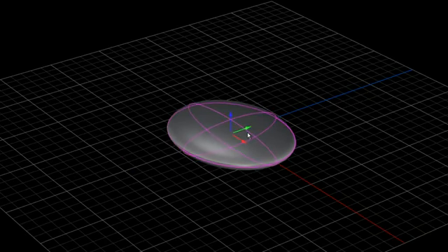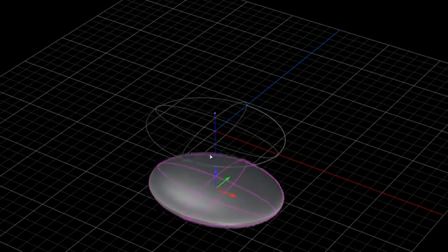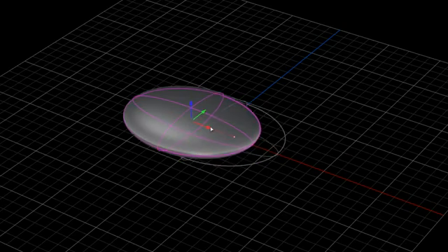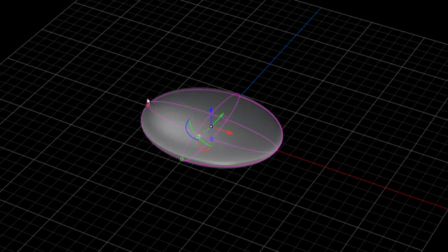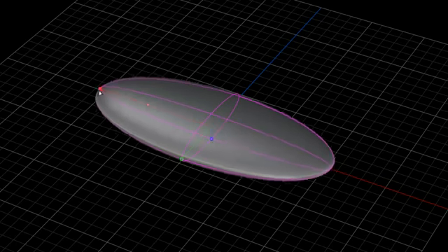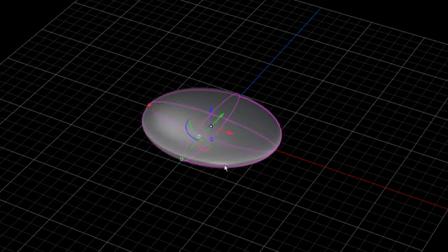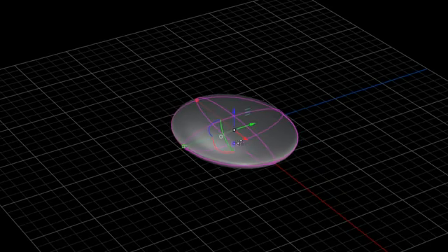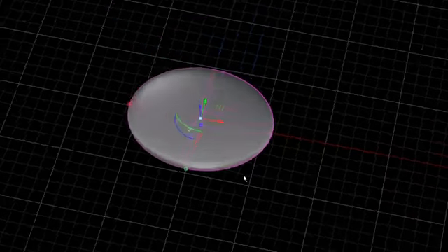If anyone has used our MSR controls or the T-spline HUD manipulators, you'll be very familiar with what is happening here with the Rhino Gumball. Right, so you can see it allows for movement. We also have individual little spots right here for scale. As I click and drag on these, this would be a 1D scale. Okay, there'll be one running in the other direction, and then one vertically for scaling within the Z.